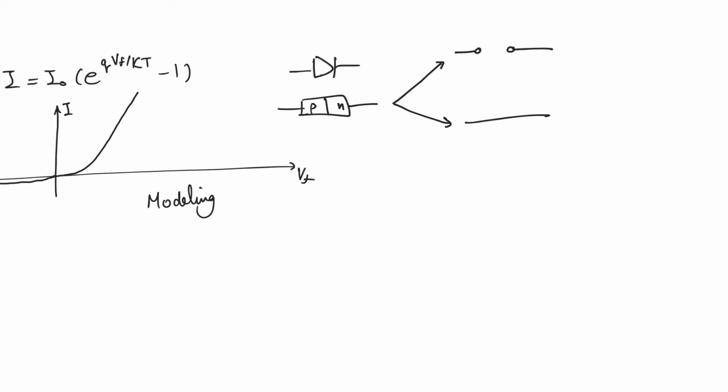And so when we say either, we mean that the diode is going to be in two conditions. When is it going to be an open circuit? When it is reverse. When is it going to be a short circuit? When it's forward. So we call each of these a region of operation. We call this the forward region. We call this the reverse region. So dividing a nonlinear device into regions of operation allows you to perhaps make it linear, at least piecewise linear, so that it is linear for each of the regions of operation.